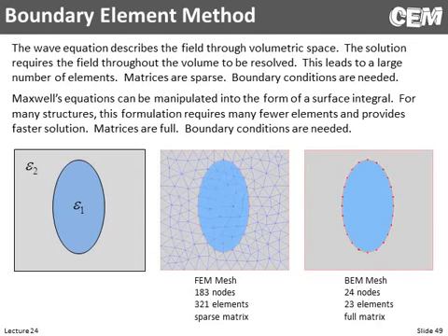That's very useful. Another thing you see, speaking of the non-boundary condition thing, you'll see hybrids of finite elements and method of moments, or boundaryless methods. So you'll resolve your device with a finite element mesh throughout its volume, but then on the very outside, you match to like a boundary element or method of moments, which then does not require boundary conditions outside of that.